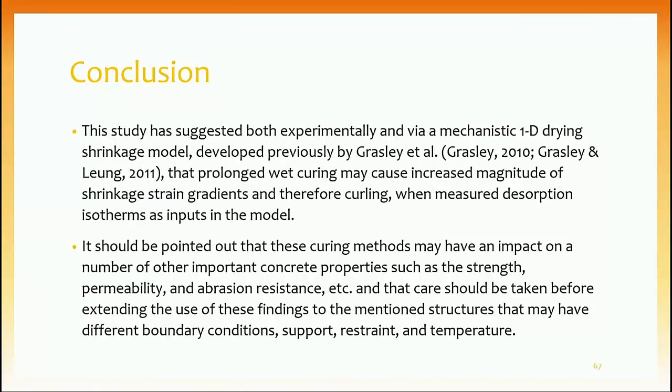there are other important benefits from wet curing for some other important concrete properties, such as strength, permeability, and abrasion resistance. Care should also be taken when applying these findings to samples that have different boundary conditions from the samples that we used in this study, such as different support, restraint, and temperature.